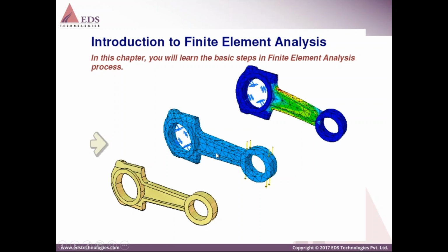Small elements are created. The discretization can be 1D, 2D, or 3D elements. In this case, these are 3D elements. After this discretization, that is the meshing, we have to provide the boundary conditions, the restraints. Then the loadings are applied onto the part.